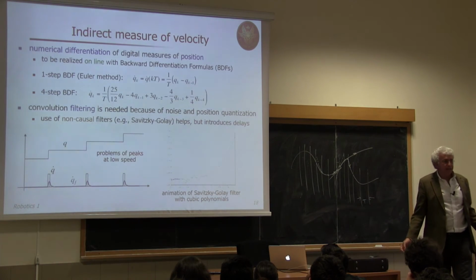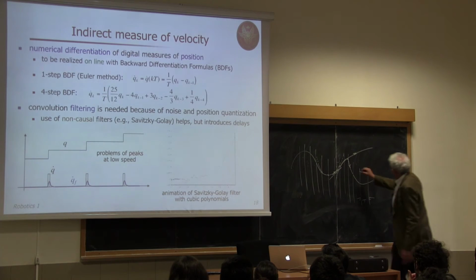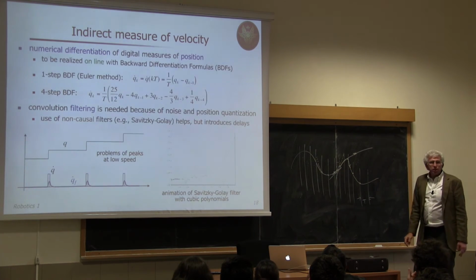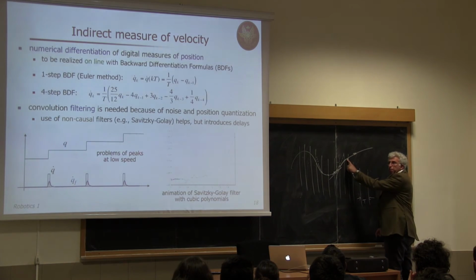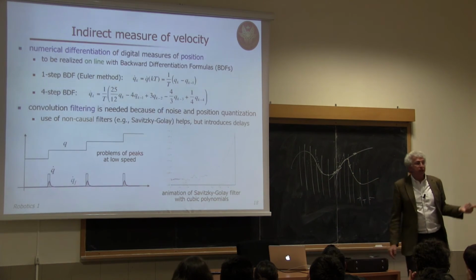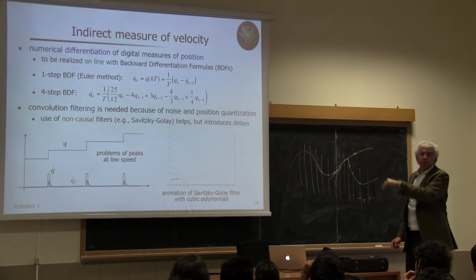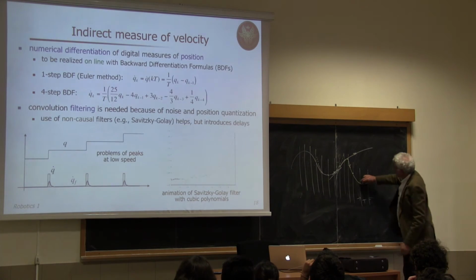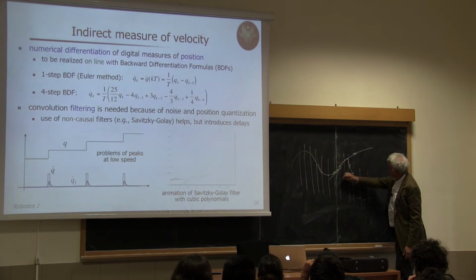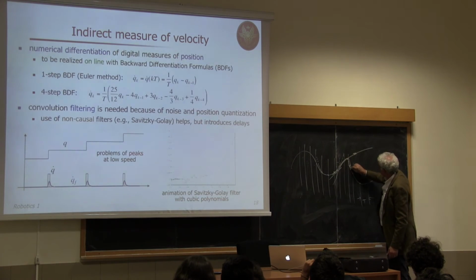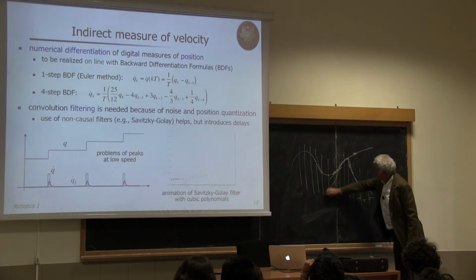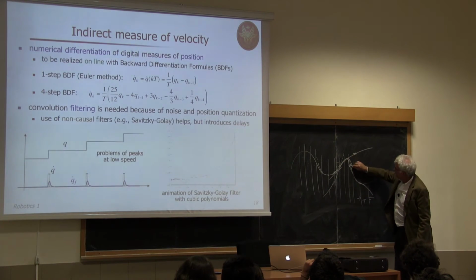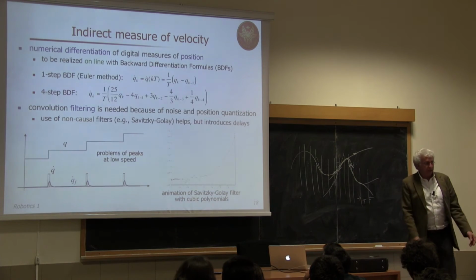Okay? As simple as that. Now, if you have available also, let's say, two more samples after the current one, and this is possible only if you're processing your data once the motion has completed, so offline, then of course you can use a higher order interpolation, and your interpolator may do something like this, and then diverge out of the 5 point, and here the estimate is pretty much closer to the desired one.